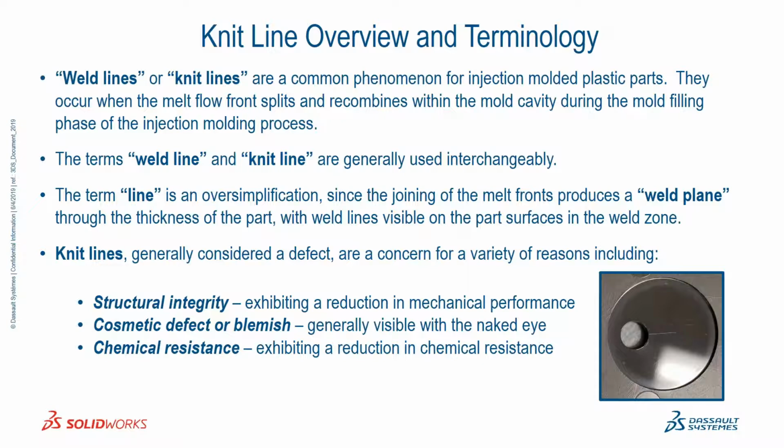There's a lot of terminology issues that could be subtly different here, but generally speaking, I would consider the terms weld line and knit line to be equivalent, and I use both terms. Probably I'll use both terms today, just not consciously, but sort of unconsciously. The term line here is really an oversimplification or almost a misnomer.